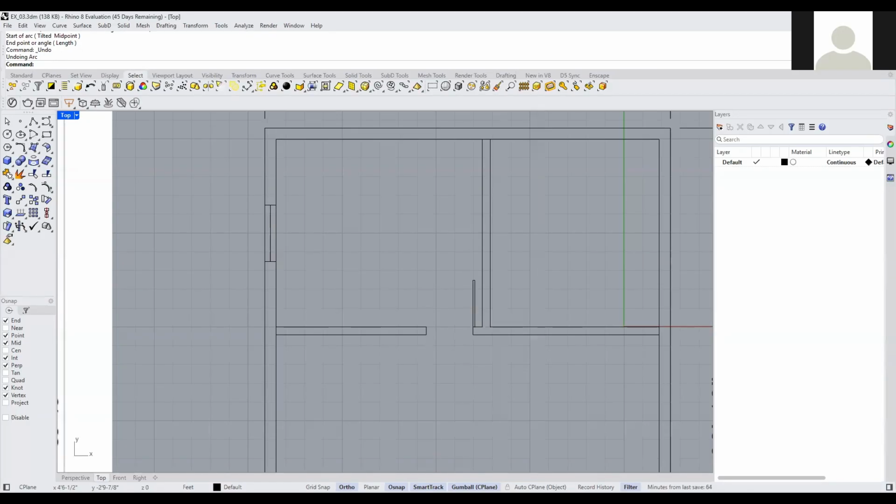Now I'm going to show you how to draw the door swing with arc. If you go to this arc command and open it up, you see different arcs. I'm going to just work with the first one. So select that and you'll see on the command bar it says center of arc. So you have to pick your center of the arc. The center would be here because the arc goes this way, right? So the center would be here.